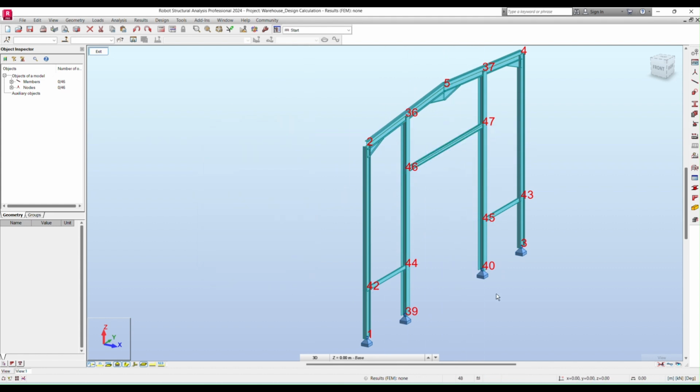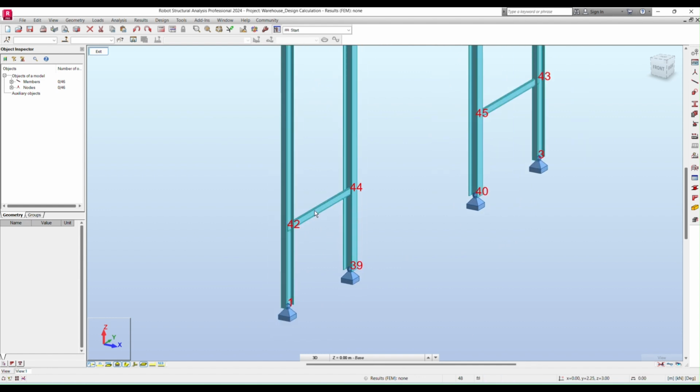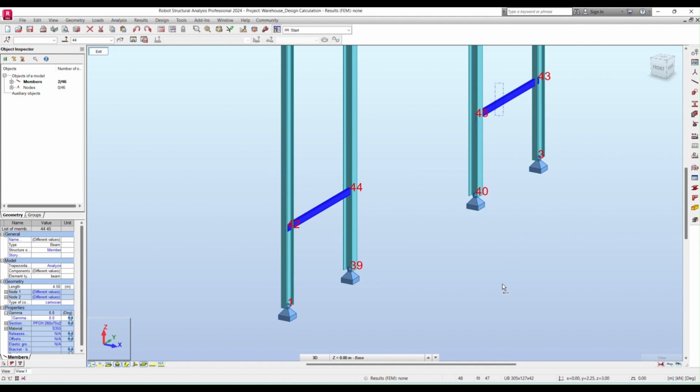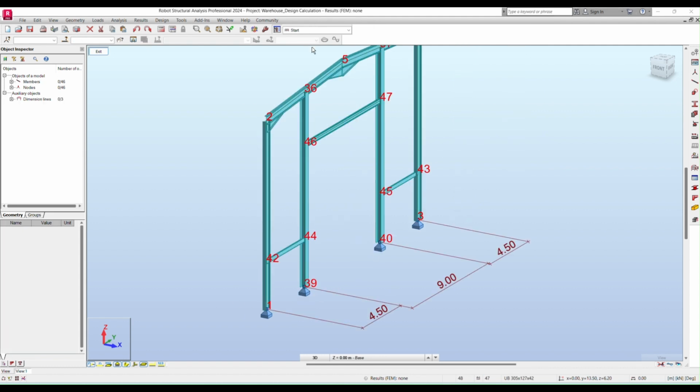So now we have done this, but however the door width is very small compared to this distance. This is 6 meter we have considered, but now it is going to reduce. We decided to go for a 6-meter wide rolling shutter, but unfortunately during the modelling, by taking the middle of the node, it is coming to 9 meters. So let us consider the same as it is for the demonstration, and we need to add some 2-meter distance,